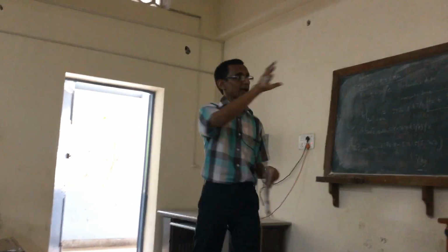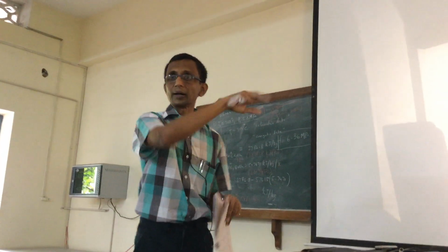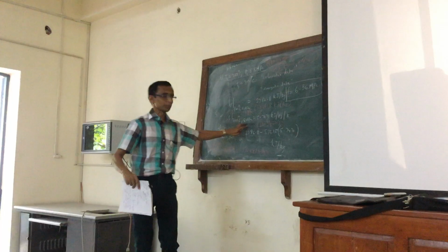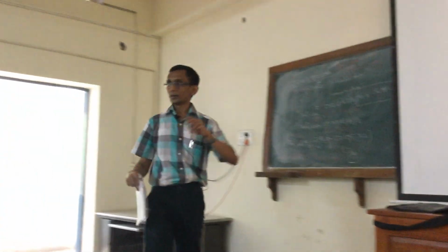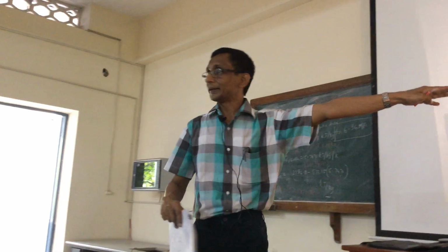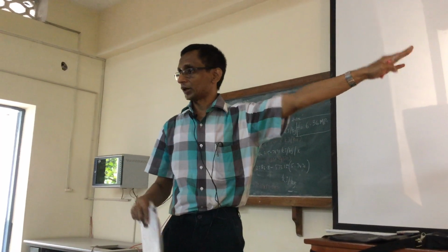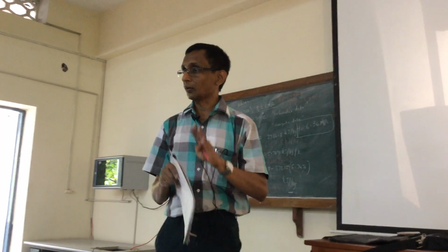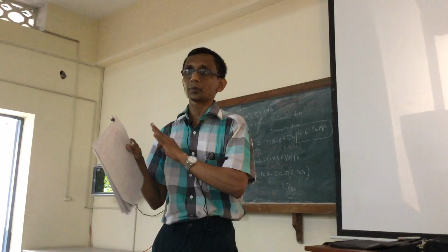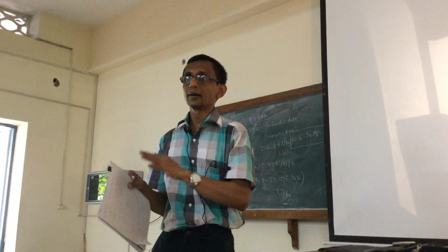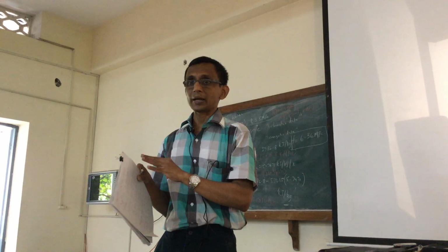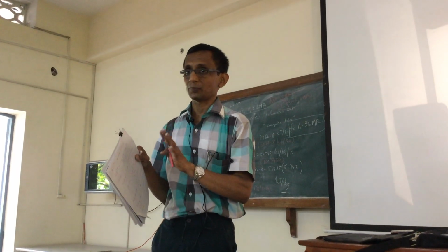So what I do is calculate the difference from the tables. I've already calculated what I want from the tables here. I put that on the board. You can go and verify that. And I have that other integral corresponding to the ideal gas, I've written it. So you have to plug the two together. All you get is RT1 logarithm F over P. So T1 is 300 degrees centigrade, P there is 8 megapascal. So you can calculate F from that.